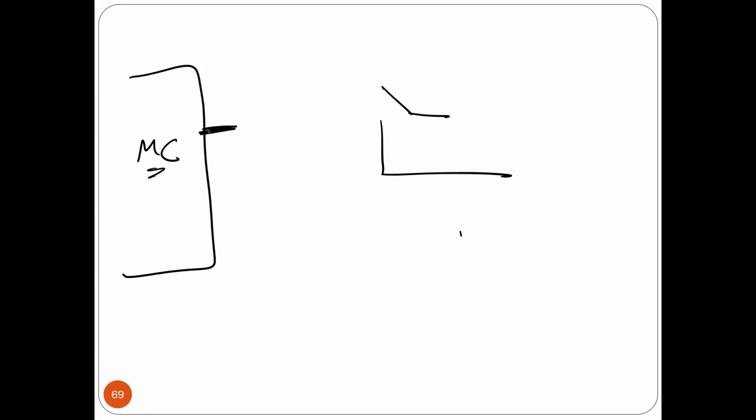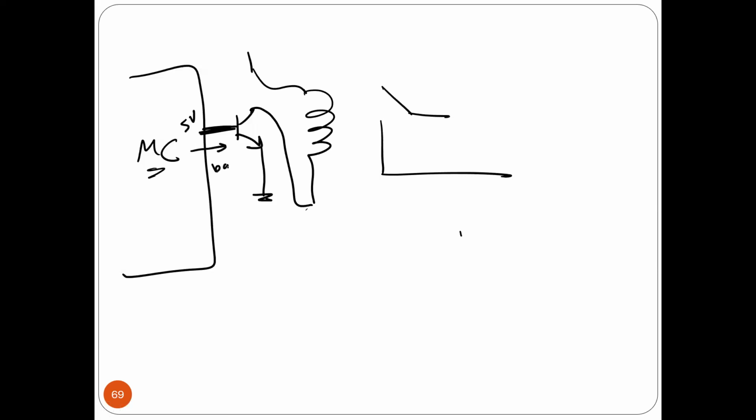So the way you are going to do it, guys, I'm going to use a transistor this way, for example, and then I'm going to put the coil here, as you see. What's going to happen is when I put 5 volts here, I'm going to turn the transistor on, and the current here is the base current. As you know, the base current is very little current, and the current coming from here is the collector current, and the collector current is much bigger than the base current.